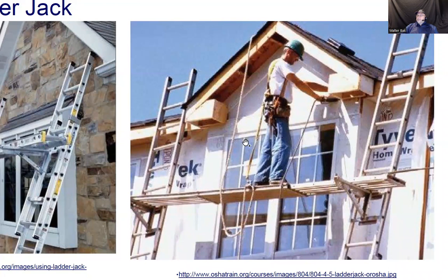Look what is going on, and then you're going to get that training, but this thing just strikes me right at the beginning when I look at this picture here, and I decided to leave that because I want to bring your attention to that. Look at where this person is tied off. Here's a lanyard, here's a harness. The harness could be approved or not, I don't know, right? Because I can see the details of the harness here. Wherever that person is tied off, what is going to happen if this person falls off this platform?